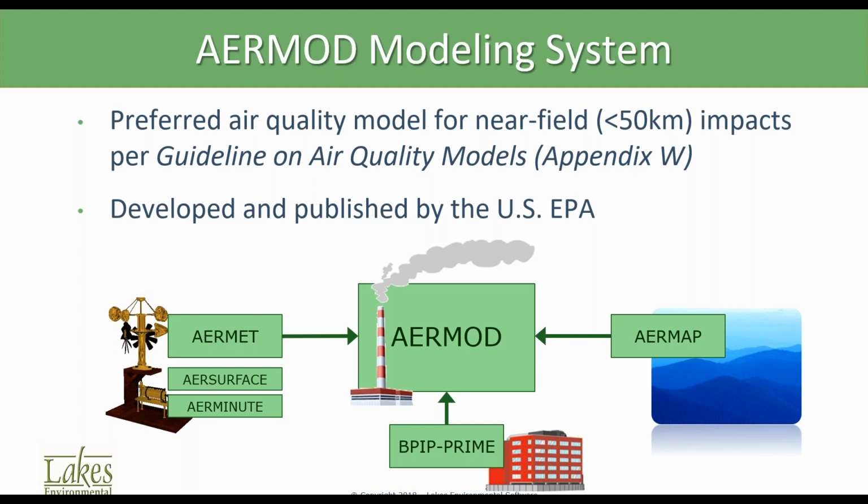AERMOD is made up of a number of components. You have the AERMOD model executable itself, represented here in the middle, into which you put in your sources of pollution, locations where you want to calculate pollutant concentrations, and a few other background parameters to calculate the actual air quality concentrations of pollutants. But in addition to the AERMOD model, there are a number of preprocessors involved, like to the left we have AERMET, because you have to process MET data in order to input that MET data to AERMOD. And AERMET also uses additional preprocessors, AirSurface and AERMINUTE.